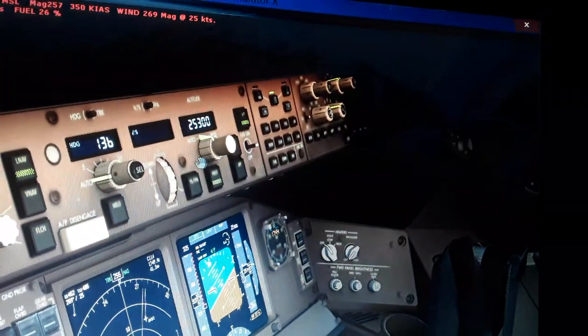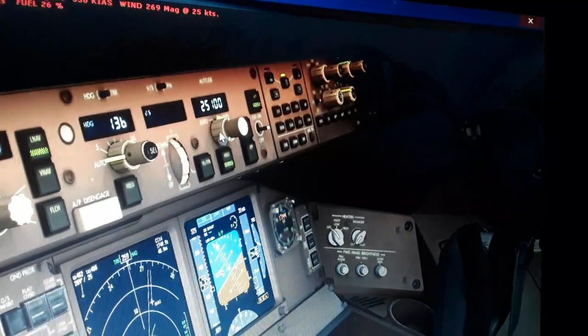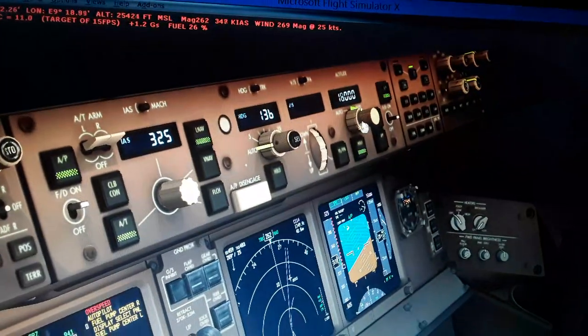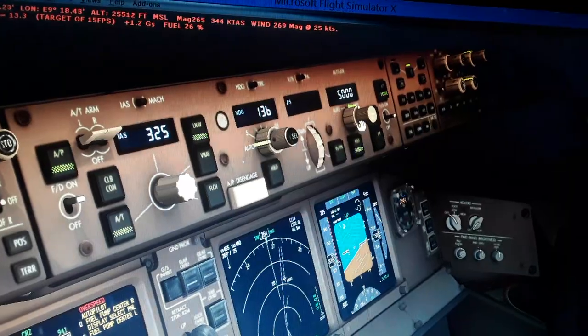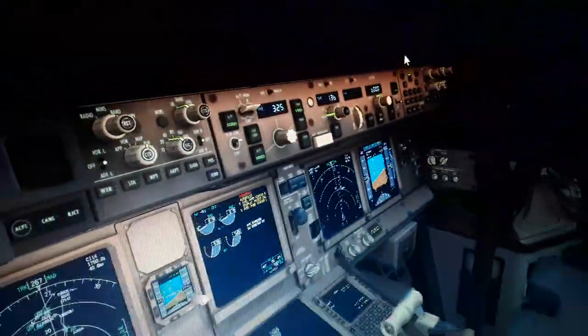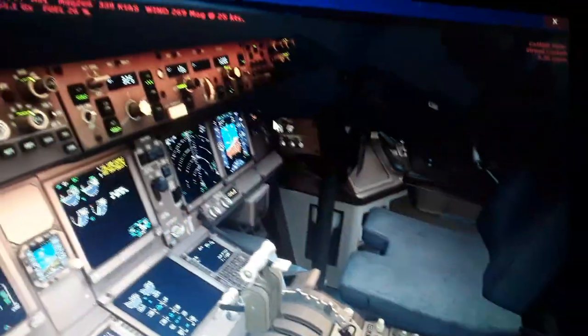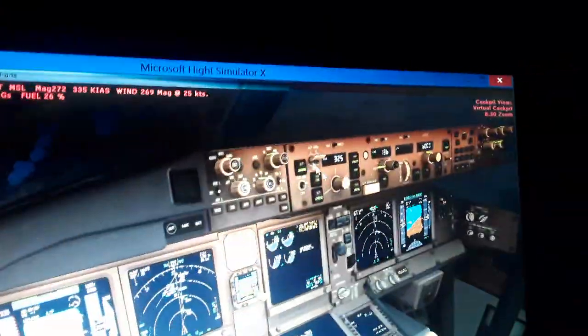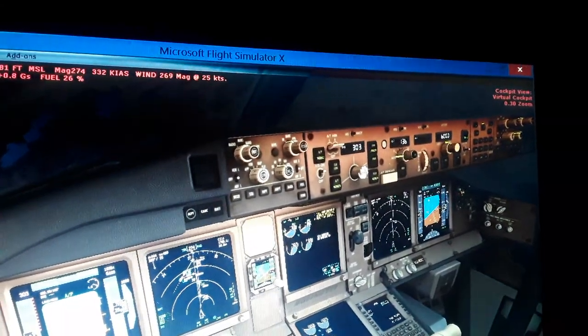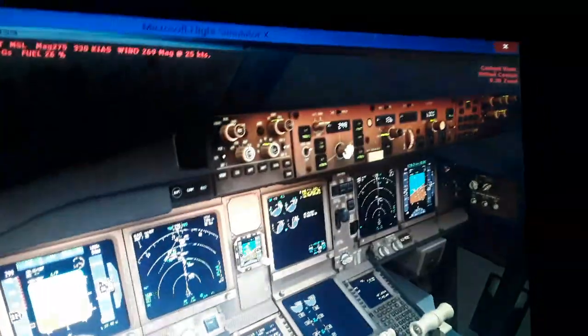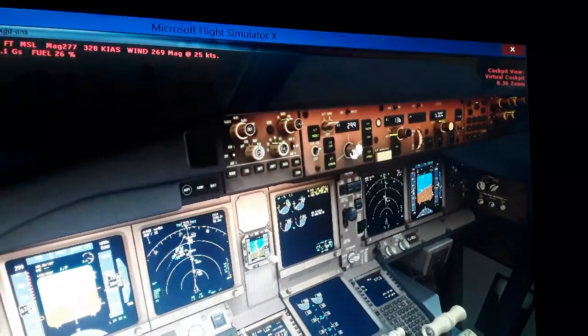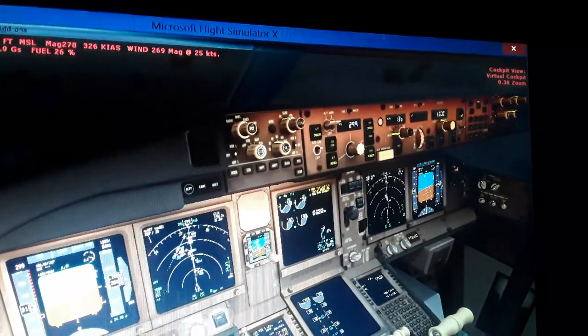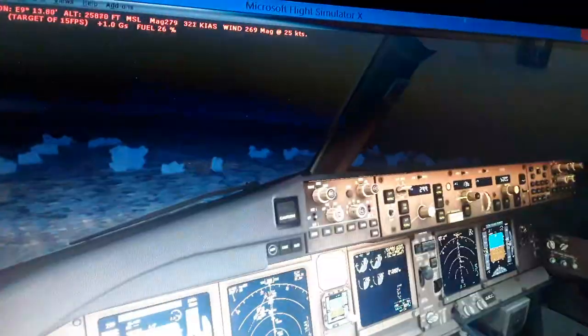Obviously, maybe select lower altitude now. For descent, so you can see we are here in the target, and select the flight level change and repeat, brake descent, and also increase the airspeed a little bit. So we commence the descent. You can see